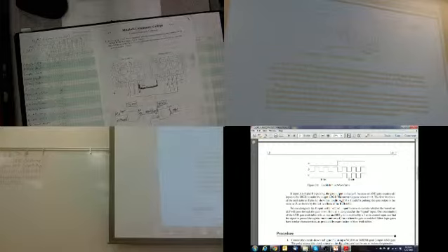Now, what does this knob do? This is called the scale. What this does is it shrinks or makes bigger the actual amplitude of the signal. Really what it does is it changes the division, but for you it makes it look like the amplitude is different. But really it's the same amplitude, because notice that this says 5 and the signal is 1 division, which means 1 square. So a square is 1 division.